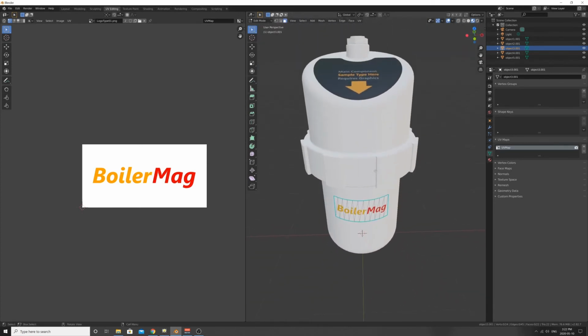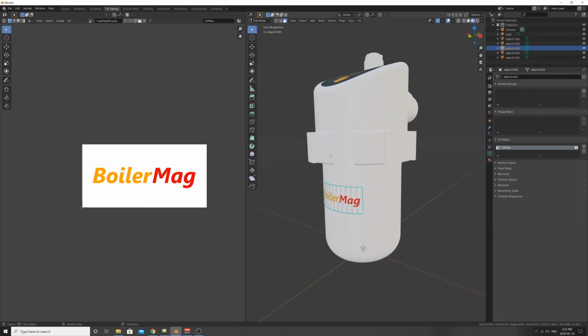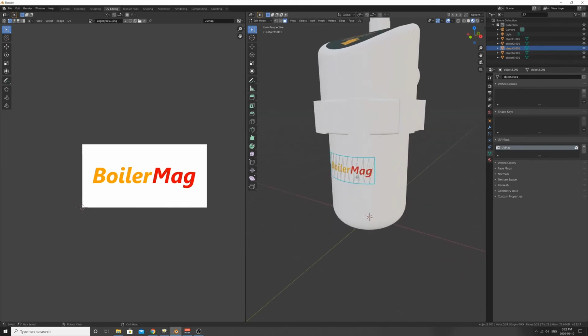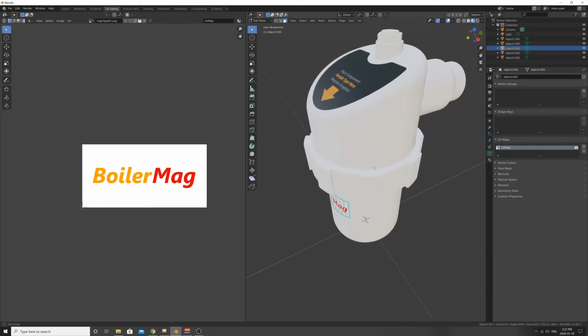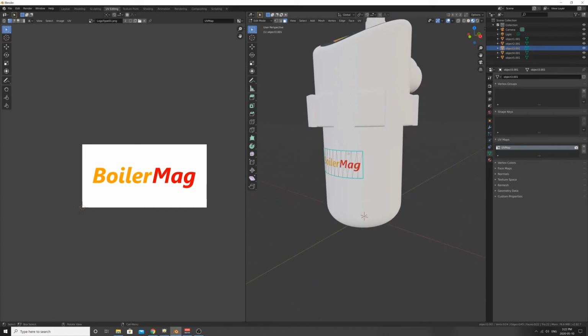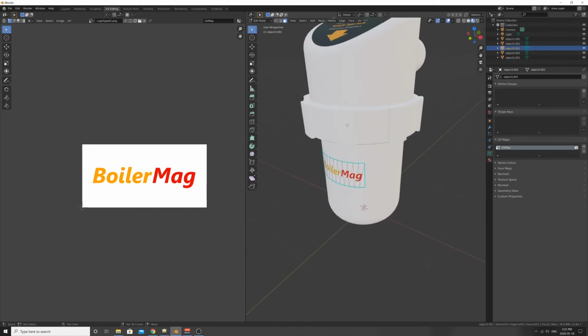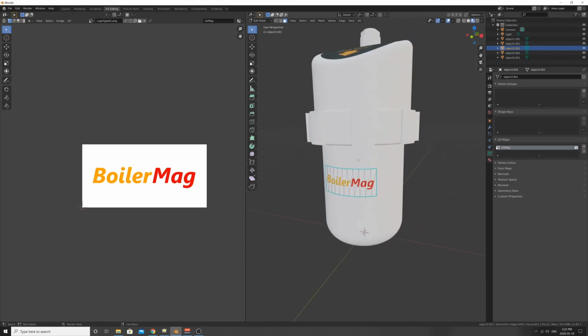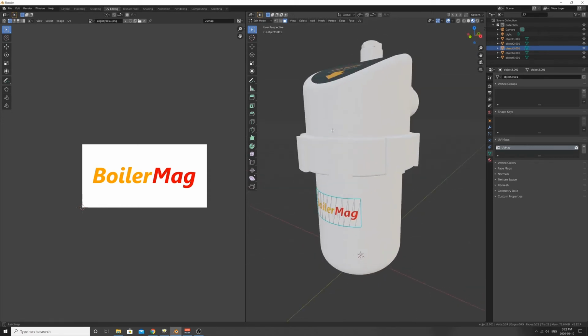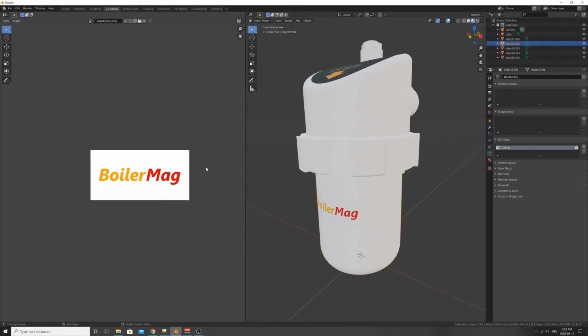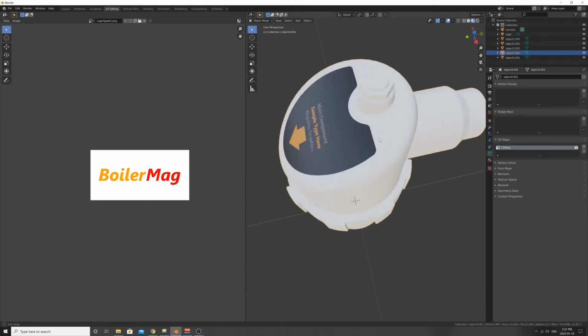The reason why we're using this method of editing the UVs for these decals is that the augmented reality render engines on iOS and Android devices don't use the decal systems that may be in Blender or KeyShot or wherever you're coming from. Those are custom decal engines that don't work in augmented reality, right? So you need to make sure that the surface UVs on your decals are correct. And now we've got some good UVs. If we go through and check each of our objects, the UVs are going to be good on each one of these.